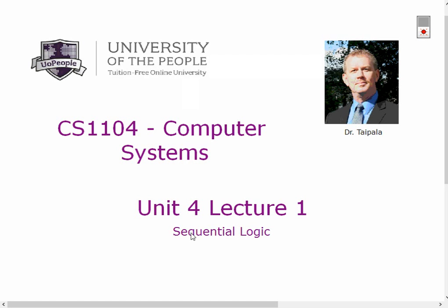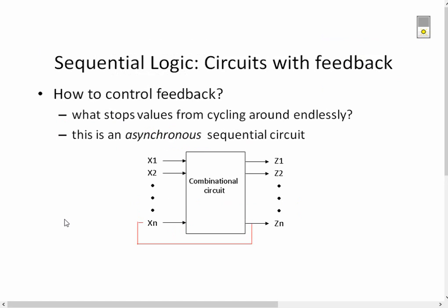The problem is that within a computer system, I do have this concept of time. I do have the clock that's going on. I do need to do things in a particular sequence. And that's where this idea of sequential logic comes in. I need to be able to retain state. And that is what makes sequential logic really different from the combinatorial logic that we've been looking at up to this point in time. So, sequential logic maintains state.